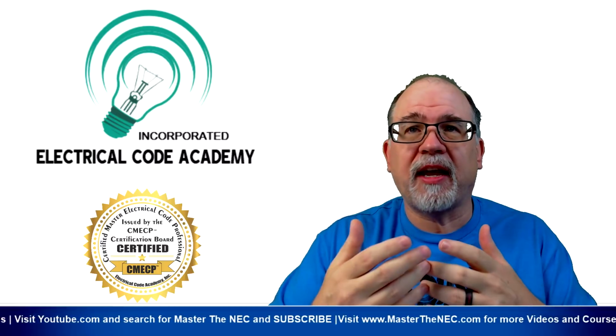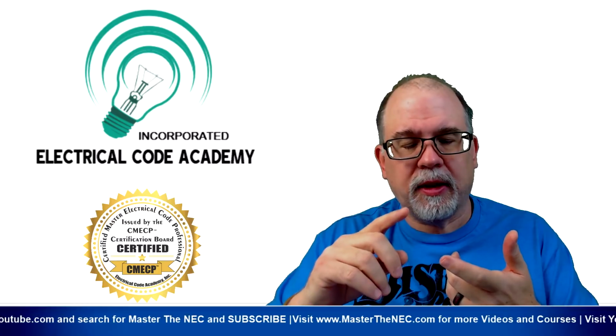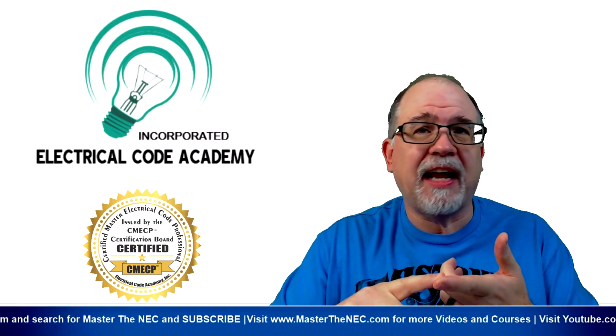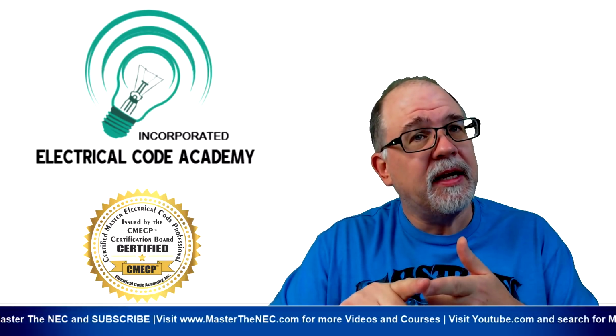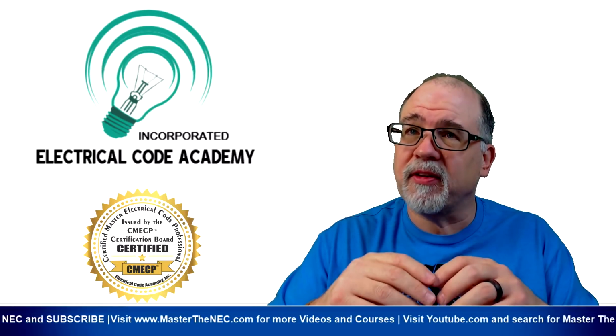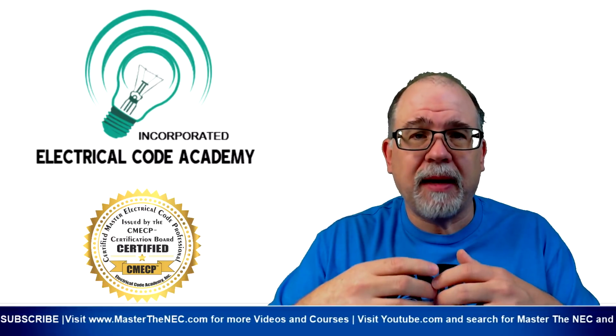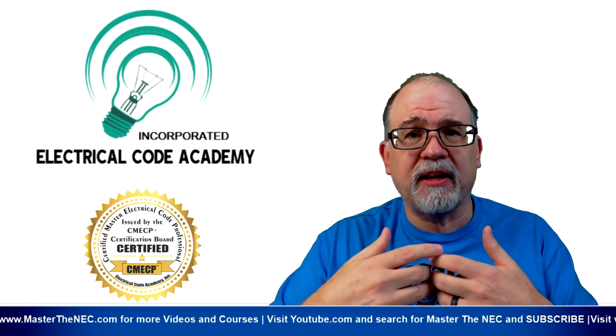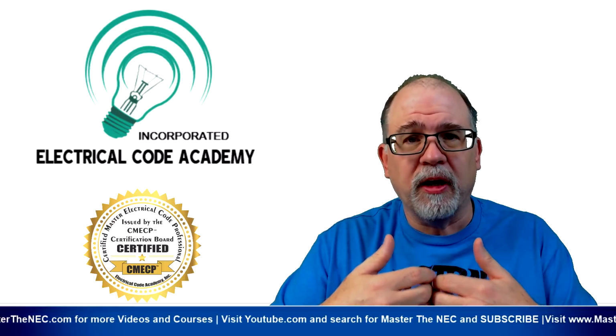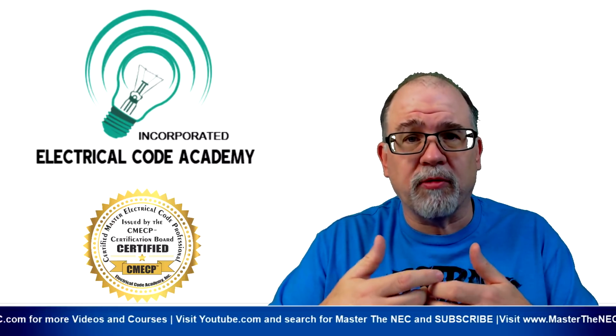If you're taking an exam and you need to know what the overcurrent protection device is under 450.3 for the transformer's primary or the secondary, you have to start out with these basics. You have to know how to take the kVA, convert it into VA, and divide it over the voltage times the square root of 3.